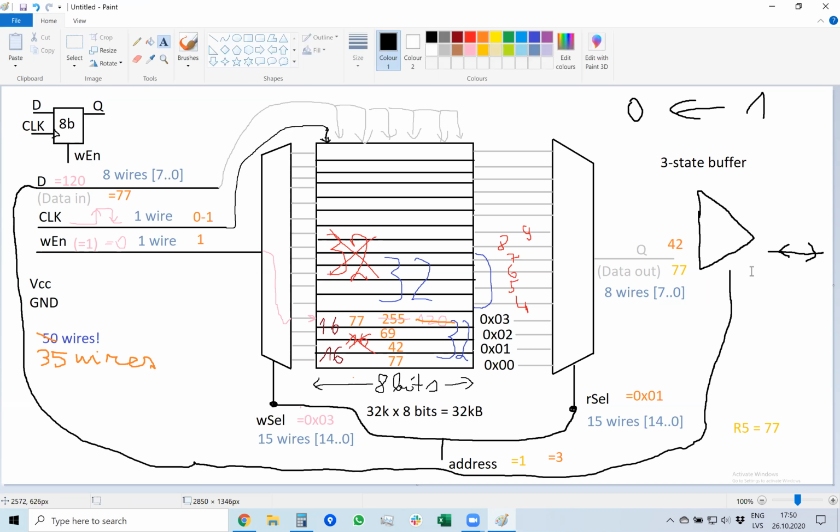And it works in the following way. Quite simple. Data connects here, so we can read whatever we output, we don't care. Data in is a high impedance reading signal, so it doesn't output anything. So it reads whatever is on the data line.